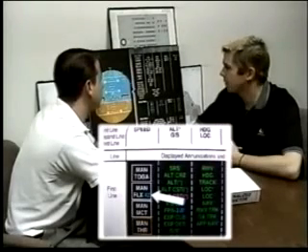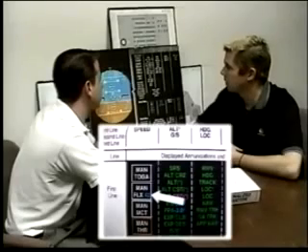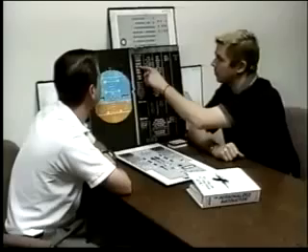What about Man Flex? Man Flex indicates a couple things to me. First of all, it indicates that the auto thrust is armed, that the most forward thrust lever is in the flex detent, but it also indicates I'm on the ground because this is during takeoff, and it indicates that in the MCDU I set a flex temperature of 42 degrees.